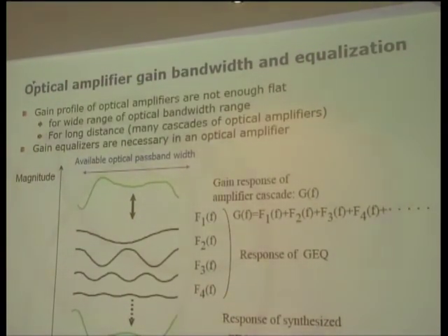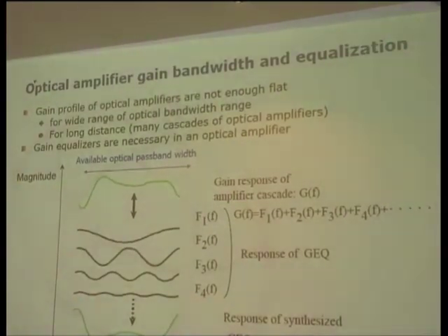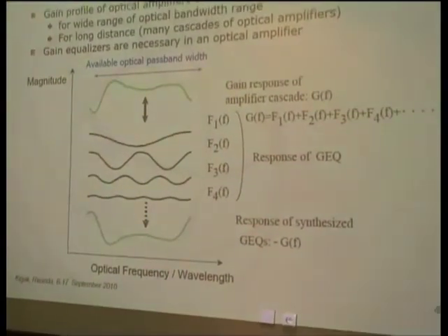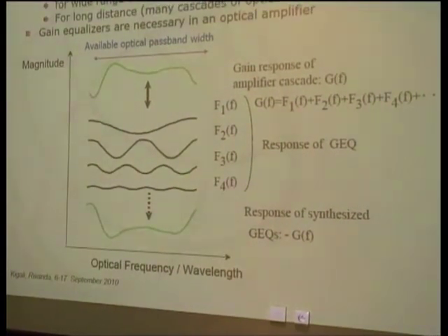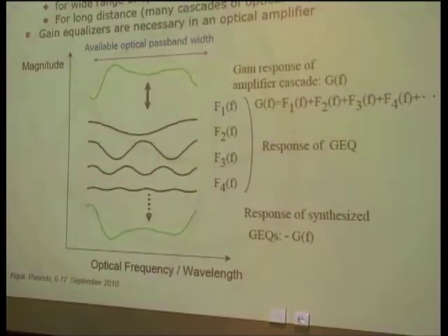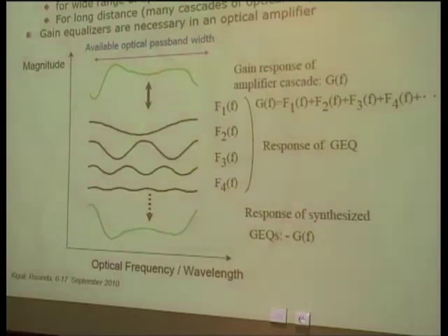Another issue is, this is not described in the handbook, but it's actually an important issue, so I added this content. Actually, an optical amplifier's bandwidth is not flat, ideally. So as the signal passes so many amplifiers, the combination of the amplifier gain spectra can change the shape of the WDM signal, so the alignment in terms of the power.